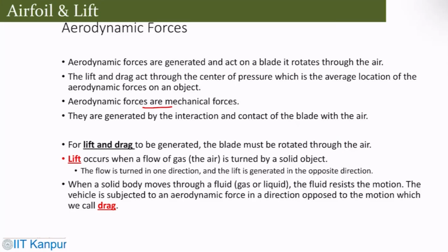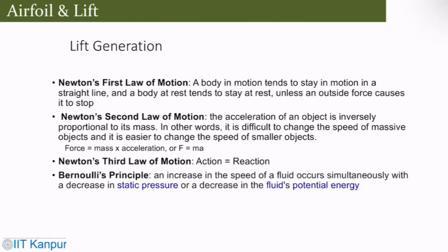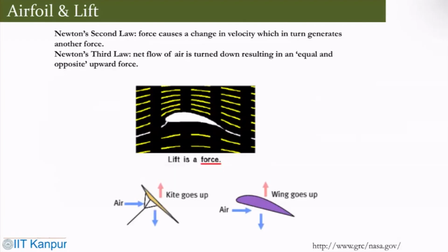So the lift generation is what we get using the fundamental principles of Newton's first and second laws of motion, then the third law of motion, and Bernoulli's principle also, increasing the speed of the fluid. What Newton's second law says is that a force causes a change in velocity, which in turn generates another force. So when the flow passes by the airfoil, there is a pressure difference.